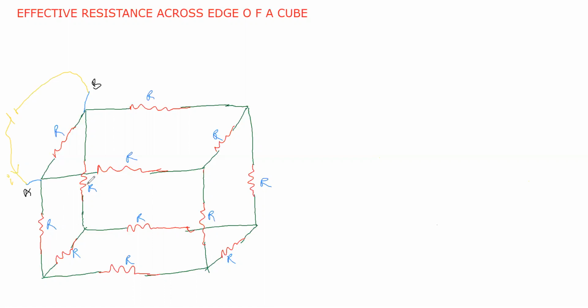In these three paths, let us see here, this path and this path are identical paths, so in this path and in this path the current should be the same. So here I dash current will be there. That means in this resistance and in this resistance, the potential difference should be the same, because the currents in these resistances are equal.